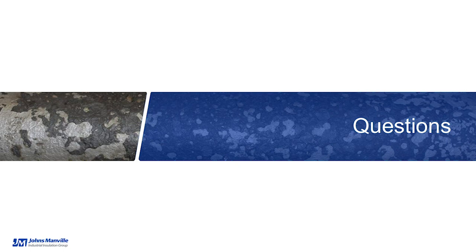Excellent. The next question we have is for you, Juan Carlos, and it actually refers all the way back to one of your early slides on reasons for corrosion to occur. They asked about the first photograph on the left. Does that indicate dissimilar metals, or is it applicable for similar metals? And so Juan Carlos is actually looking at the slides right now, and he'll run through that for us. So the answer is this is when you can have two different materials joined together. Okay, that creates different potentials.